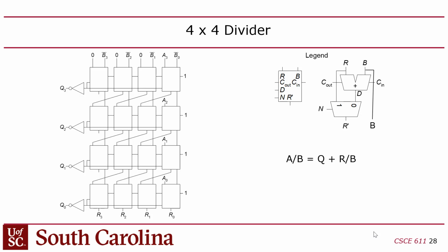Now in this case, we're actually doing the opposite here. We're taking the dividend, which is A. A is the dividend. That's the bigger number that you're dividing into. And we're shifting it right. That's why you see A3 there, right? See that A3 is in the top layer? Why A3? What happened to A2 down to 0? Well, those are not being considered in the first layer. We're just taking A3, right, which is the version of the multiplicand shifted to the right.